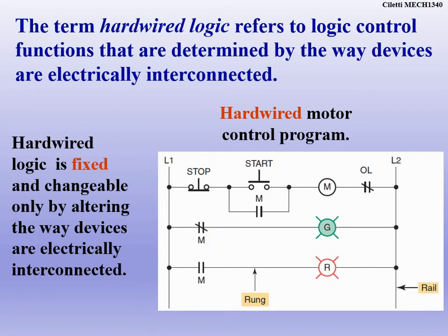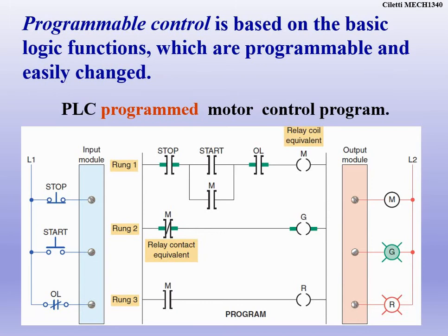Whereas when we're using our control program, everything's wired to the I/O on the PLC. So if I accidentally did that ANDing and I needed to OR something, I just change the program real quick and we're done. So that's kind of the difference. Hardwired is a lot more work, and you physically need to go take care of it, versus controlled, where everything's already wired to specific I/O. We just change the program real quick and re-upload it to the PLC. So everything that we do here in the PLC is using the logic that we've learned.